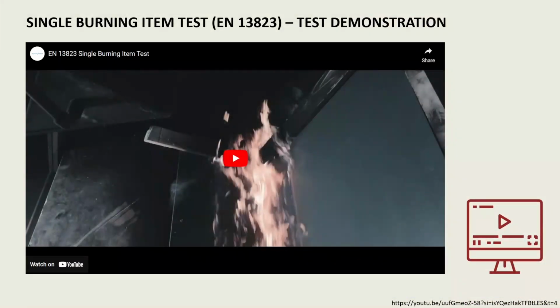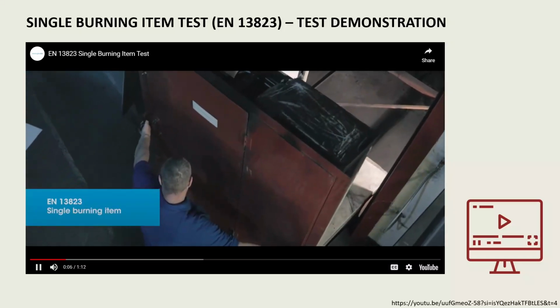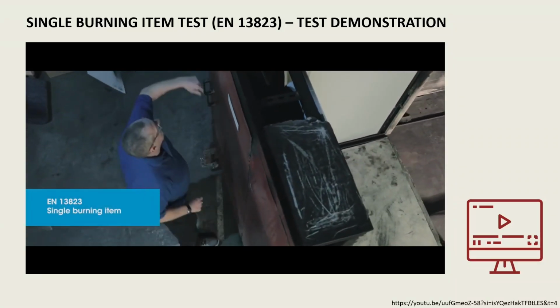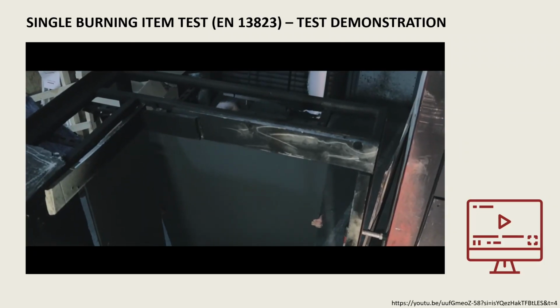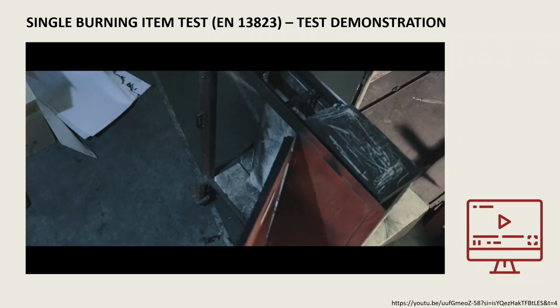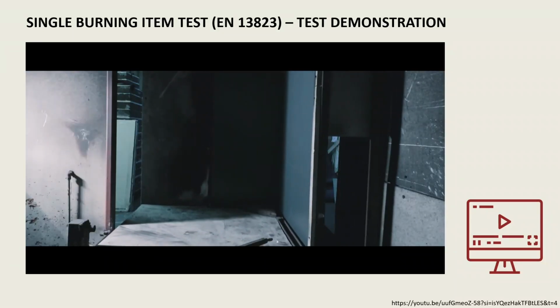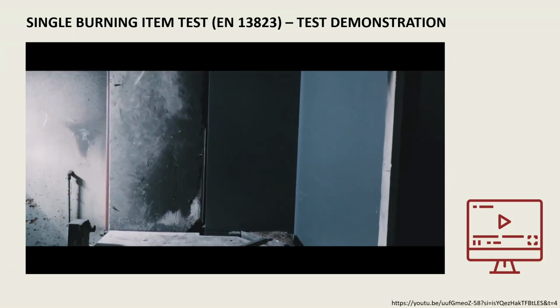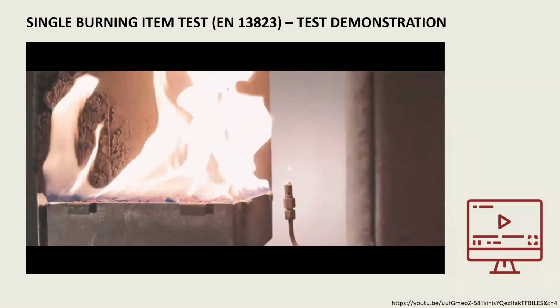Here is a video of a single burning test to help you visualize the test procedure. The EN 13823 standard is commonly referred to as the SBI test, where SBI stands for Single Burning Item. The ignition source that's used in the test is designed to replicate a waste paper basket fire in the corner of a room, and the burner has a power output of 30 kilowatts.